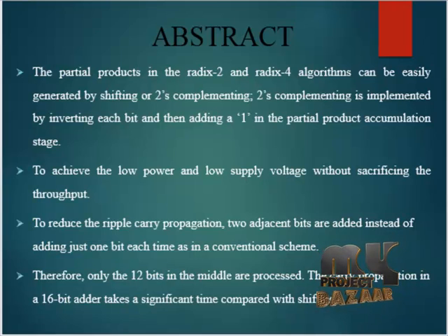In our process the Booth multiplier consists of stages: multiplier encoding, partial product generation, partial product accumulation, and the final addition. In the Radix-8 Booth algorithm, the partial products are generated by the multiplier encoder and the partial product generator. Moreover, a tree is used to implement the sum of the partial products to reduce the total multiplication time.